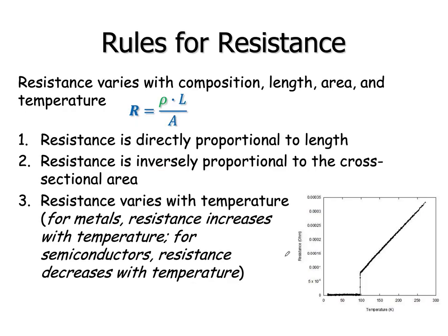So the other thing I got to mention about this is that calculating the resistance is not too bad with this equation, but in reality, resistance also varies a bit with temperature. For most materials, it increases with temperature. So as you heat up most metals, the resistance increases. For semiconductors, like silicon, the resistance actually decreases with temperature. There become more free electrons as you warm up semiconductors, which causes some problems.